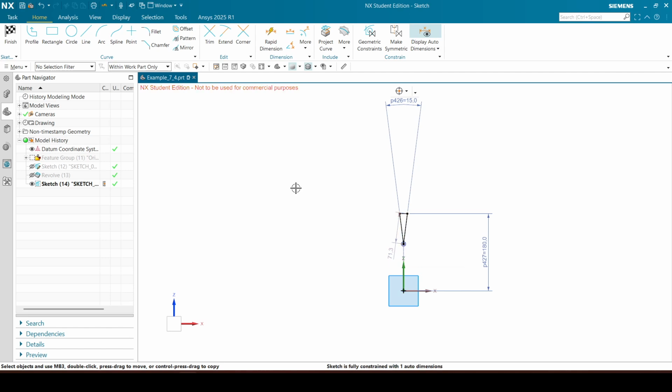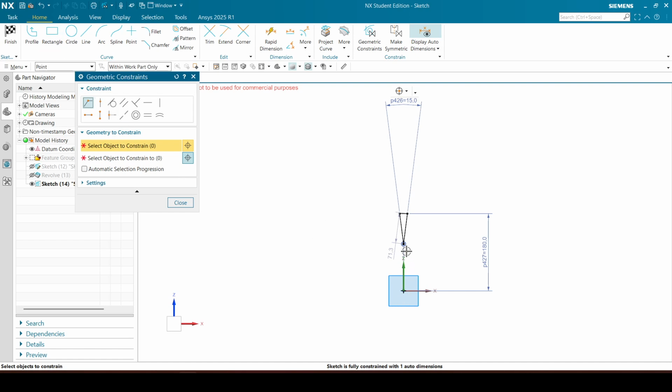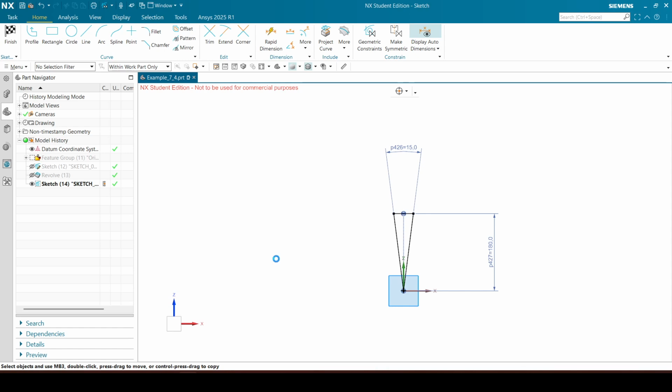So that's why it's better to add the fillets in here now rather than trying to use edge blends at the end, because if we have these now, I'm going to click C, and then I can see I'm on coincident. There we go. So now if I cut this out, then essentially I will have this point where nothing sort of exists, and then it could break my model because it then has a bunch of essentially points where nothing exists all coming together, and it can confuse NX.